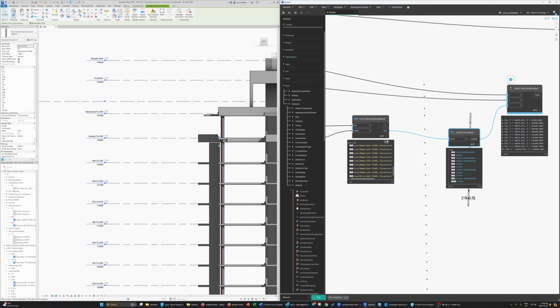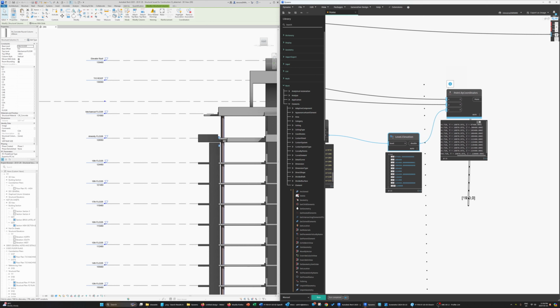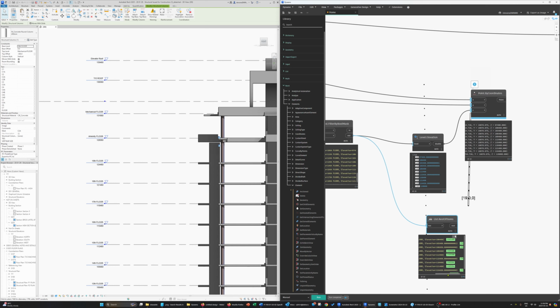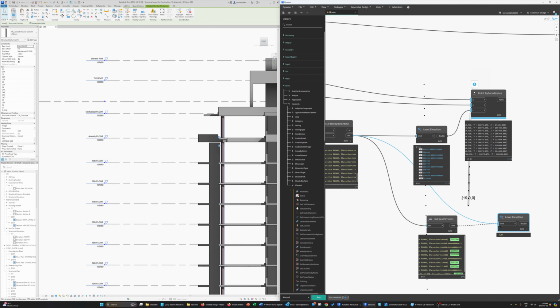I need to drop my first item. So on my second list, my starting point that's related to my end point, my second point here, becomes my end point in the first place on my second list. So what I'll do is use a node called rest of. Usually this removes the first item from a given list. So if I take my out results, I'm going to extract specifically this one. I could have bypassed this and just used the elevation marker, but I'm going to do this the long way. Later on, we can optimize some of these things.